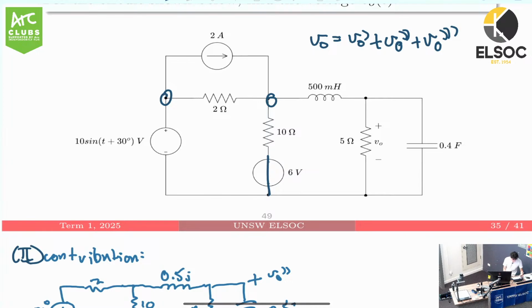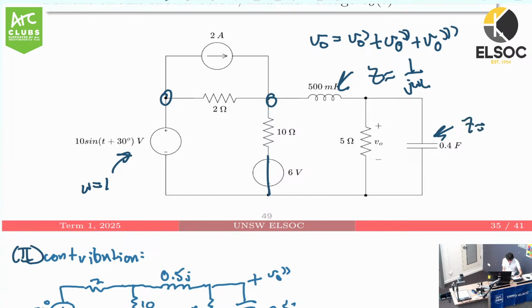And now because we're working in AC, this has an omega that's equal to 1. In AC, inductors and capacitors aren't just short circuits and open circuits respectively, because they're defined by their impedance. So that's going to be Z is equal to, oh, that's not right. That's just j omega L. And this is 1 on j omega C. And then what you can see is that omega is variable, and so these sort of act like resistances now.